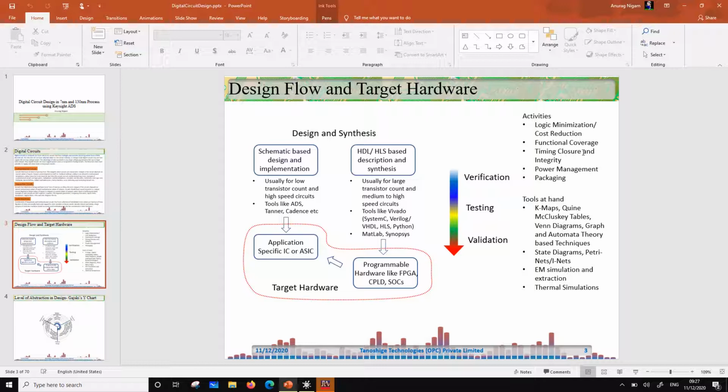That will basically decide the highest operating frequency. Now this is called timing closure, and when signals propagate between input and output, they go through degradation, right? That is referred to as signal integrity. So we design for a certain signal integrity, right? We can tolerate certain errors, so that is a limiting factor on signal integrity.